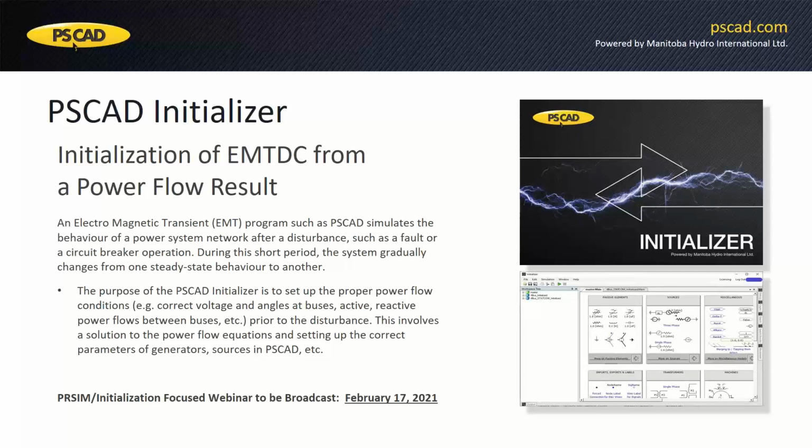What it will do is take your PSCAD case, create a powerflow file, solve it, and then use the solved data to overwrite the parameters of the sources and things like that in your project, so that you can launch your PSCAD case from an initialized state.